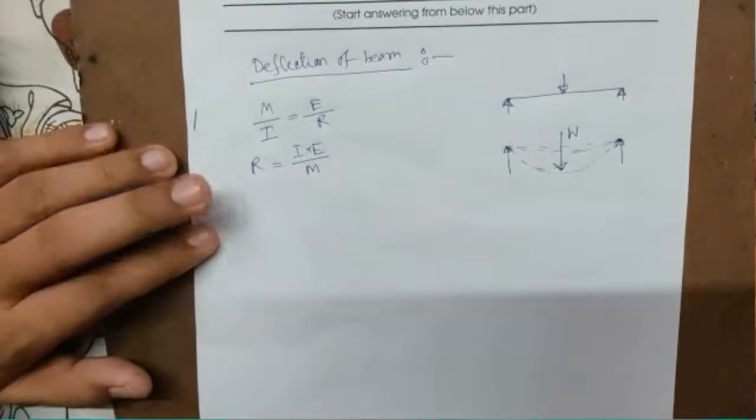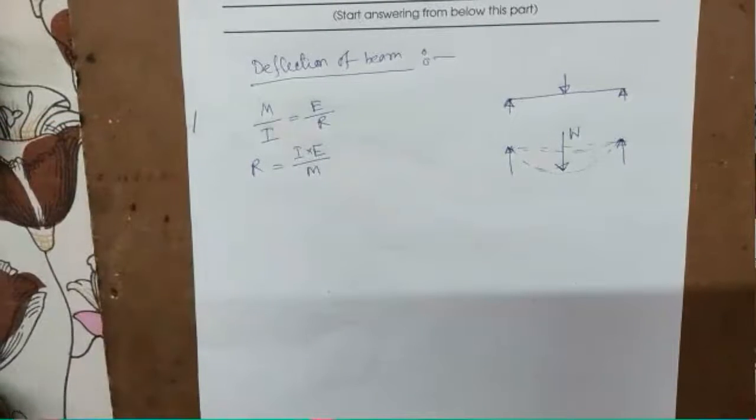So that means the beam will take a radial shape with the radius of curvature as capital R only when the bending moment M is constant. So the beam, when loaded, if this M by I is constant, will bend in a circular arc. So in that case, if we consider our study,